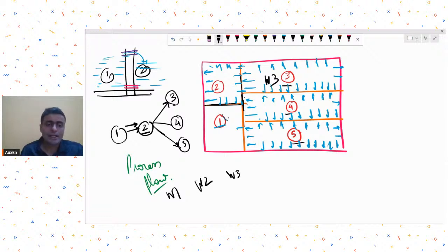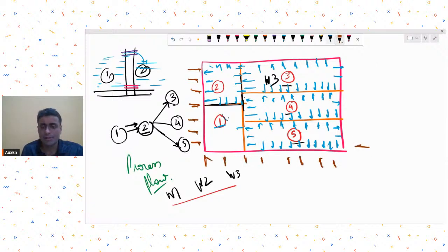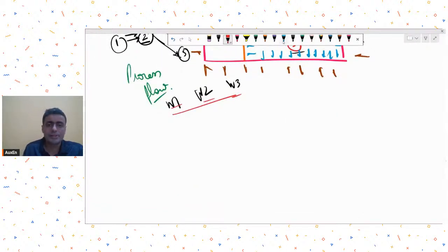So in this manner, I have made three different possible load cases. Imagine this was an underground tank. The earth pressure will continue to act in all these cases from outside. There is no variation in that. So once I have these three load cases, W1, W2, W3, after exploring all the possibilities, these are the three load cases that we have made. Now we will combine them in the load combinations.